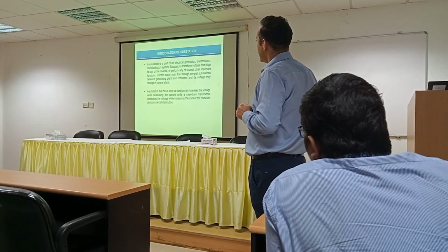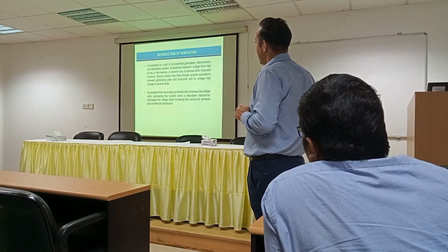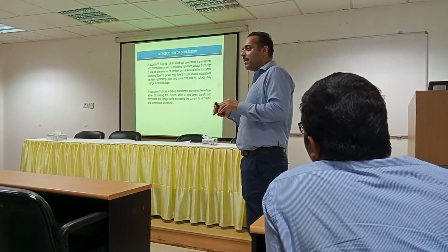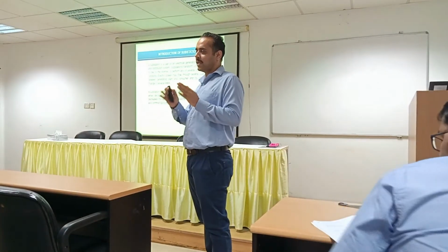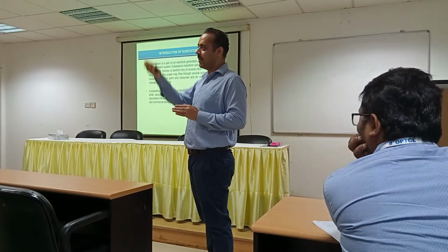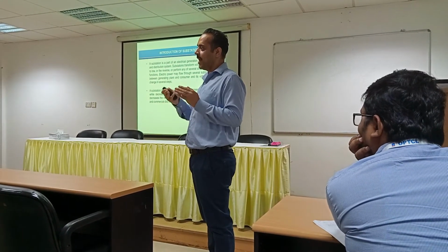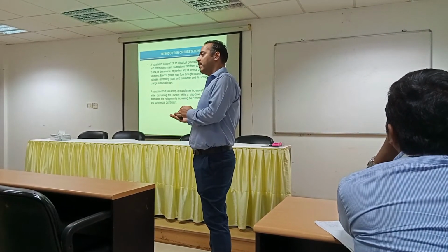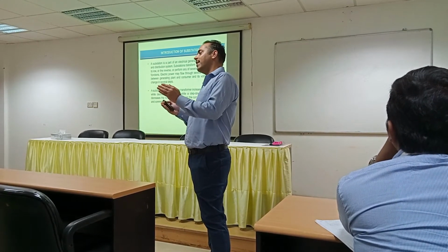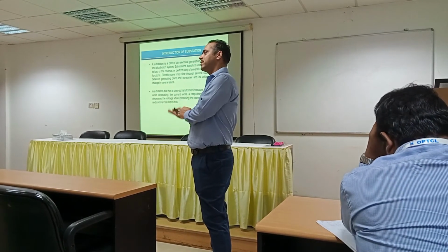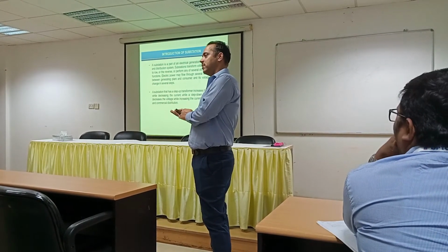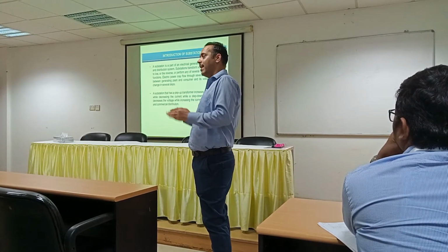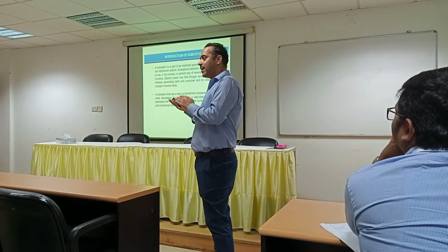Substations transform voltage from high to low and reverse, and perform several other important internal functions. In any substation, we are either stepping up or stepping down, right? We have transformers wherever the Discoms are coming. Say a 220 kV line comes into that substation, and we have to step down, because the Discom system starts from 33 kV. Then they step down again to the 415 V level, so that the consumers can be served.